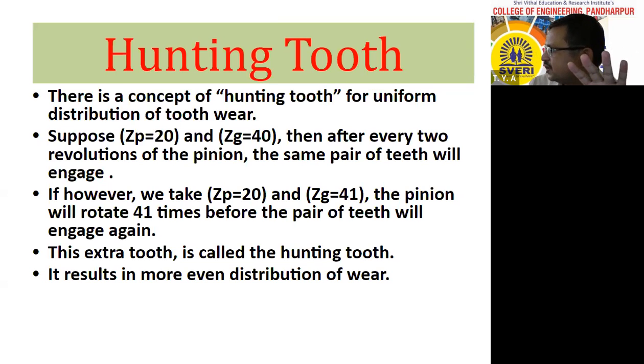This extra tooth is called the hunting tooth. It results in more uniform distribution of wear.